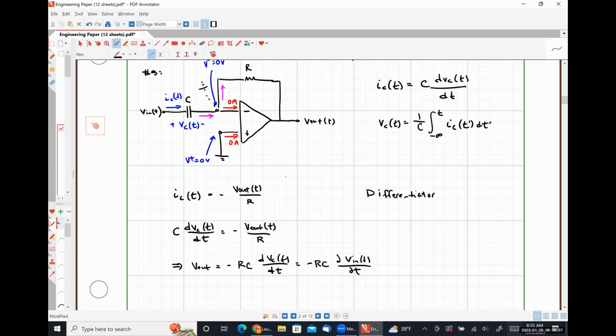We could also realize this circuit using an inductor, but the inductor would have to be in the feedback position because the current and voltage relationships are inverse, so the position of the elements has to be inversed as well.